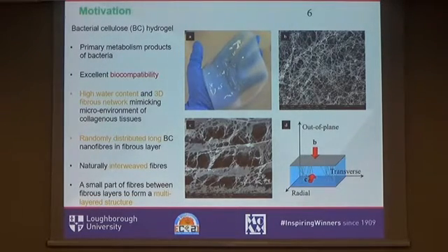First of all, there are different ways to deal with this material. Many people work with the dried material. They prepare the specimens, put them into the system, and test the properties. But then they are removing a component which mechanically you can consider not load-bearing, because water has only a significant bulk modulus and no shear modulus.